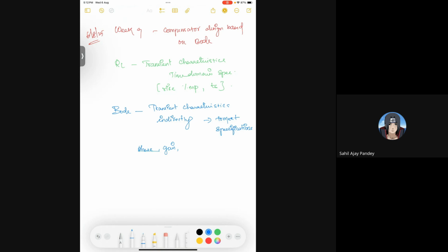In frequency response design we would have studied two different methods, right? One is Bode, another one is Nyquist plot, otherwise called polar plot also. When a compensator is added to any system, if you use a Nyquist plot, that does not retain the original shape, and therefore we need to draw a new Nyquist plot every time we make some changes in our design. So this will take some time. On the other hand, if you use a Bode plot, it can be simply added to the original Bode diagram. Thus, plotting this Bode diagram will be very easy.